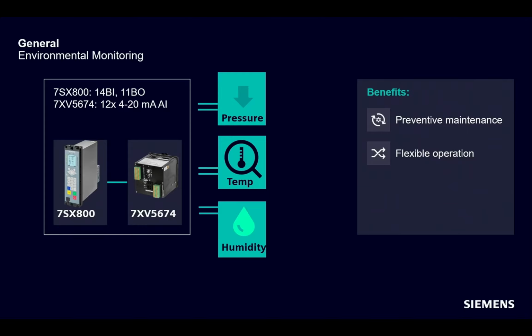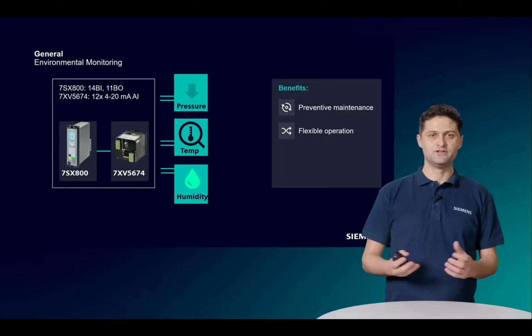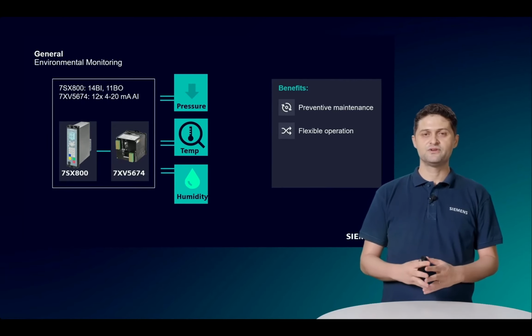In medium voltage, it is generally a source of failure when there is a loose joint or a worn-out installation in the cable compartment of the cubicle. Such imperfections in time cause heat building up and the joints evolve to bigger failures. However, such heating issues can be detected with temperature monitoring before it really becomes a more catastrophic failure.